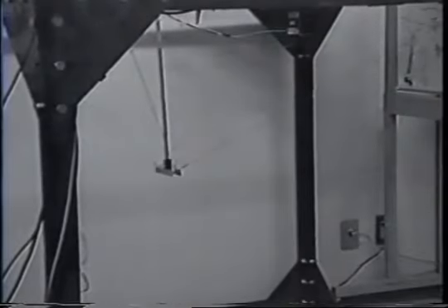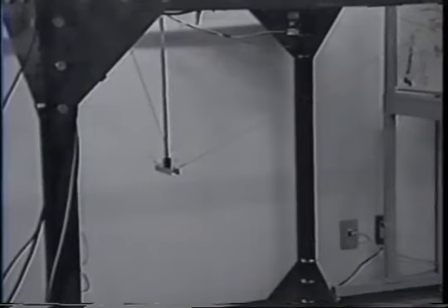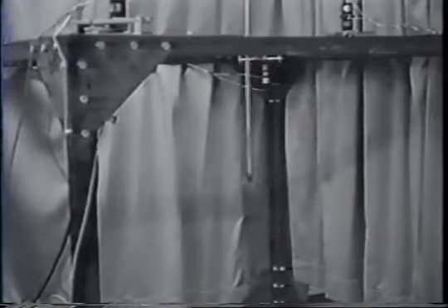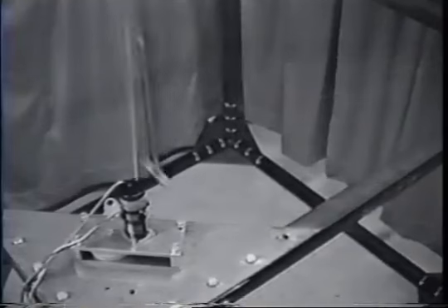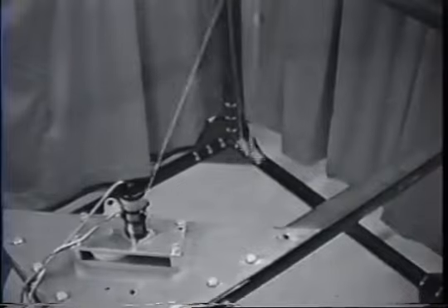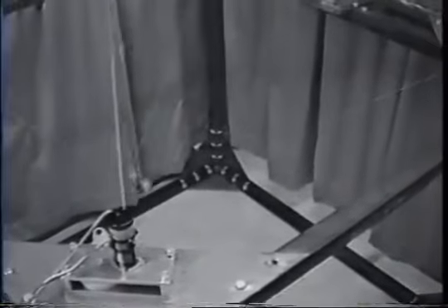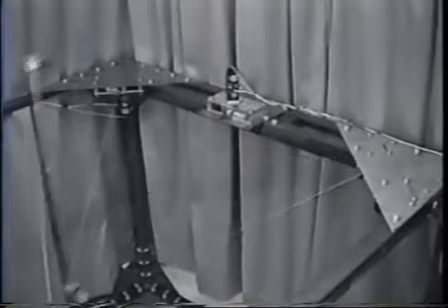The parallel wire drive system utilizes wires instead of links to control an object. Wires are employed to extremely reduce mass and inertia for achieving ultra-high-speed operations. However, since wires generate only tension, or wires have one-directional actuation, redundant actuating mechanism is necessary.